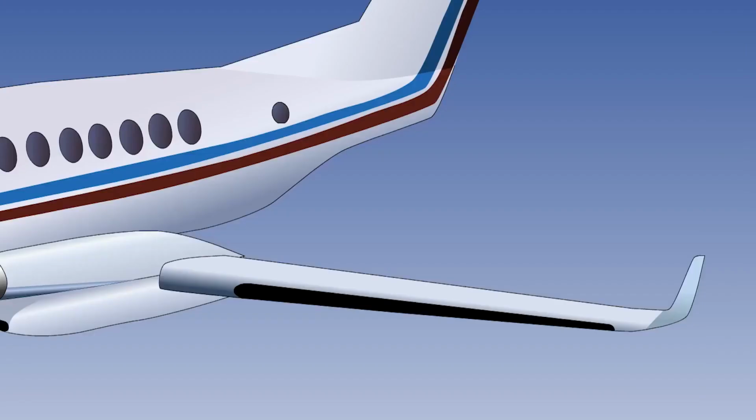From what you have seen in this lesson so far, you will know that induced drag is low at high speeds, but at low speeds it comprises over half the total drag. It has also been shown that a high aspect ratio wing reduces the strength of the wingtip vortices for a given lift force, but that there are practical restrictions, both structural and aerodynamic, on very high aspect ratio wings. So other methods of reducing vortex strength have been devised.